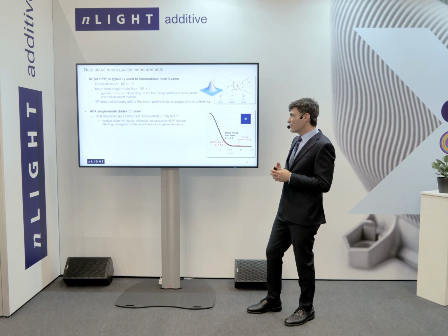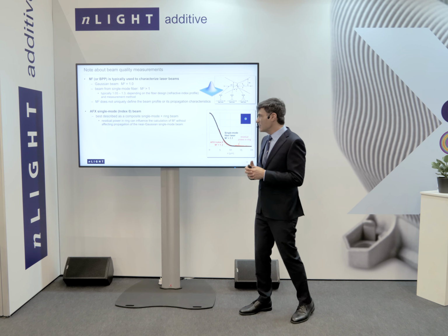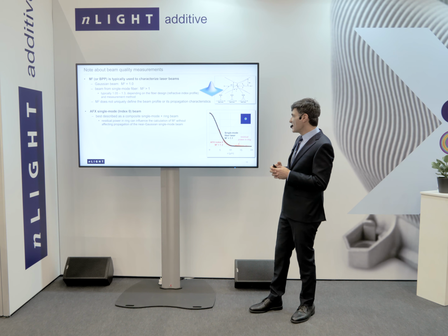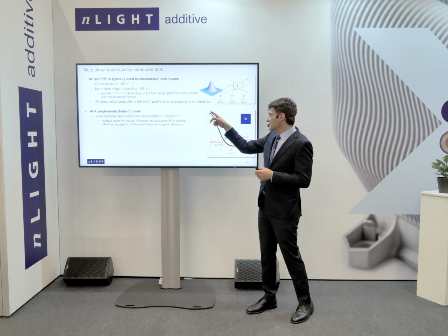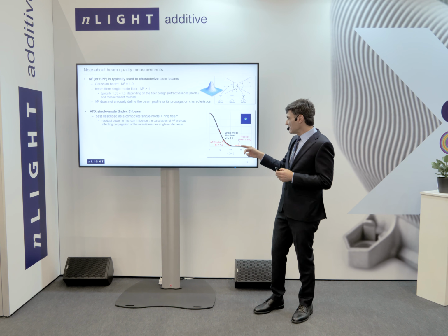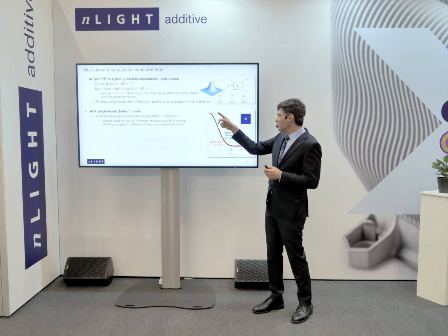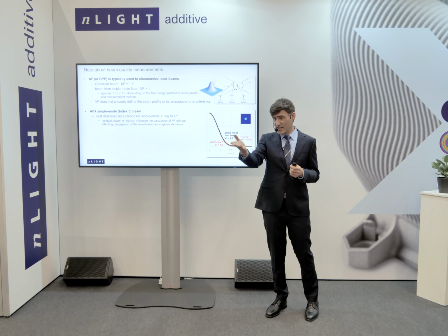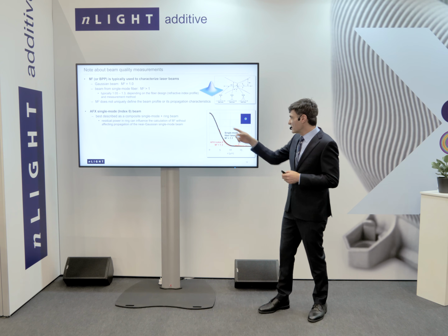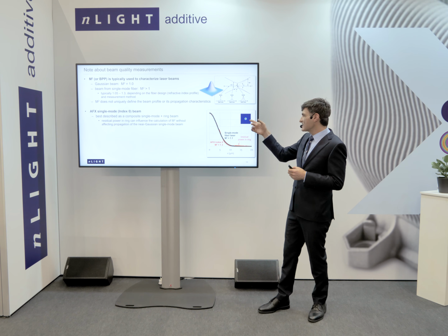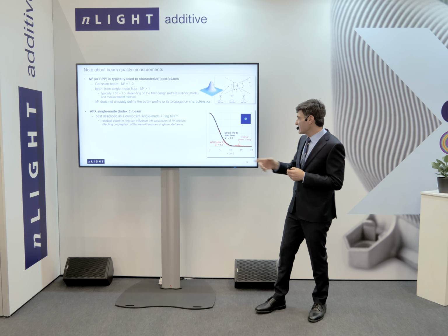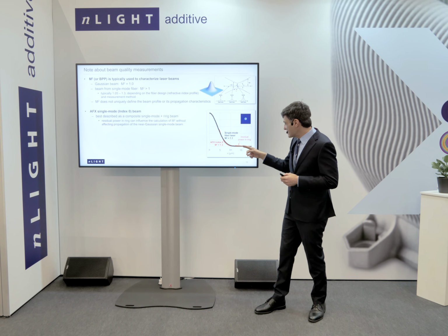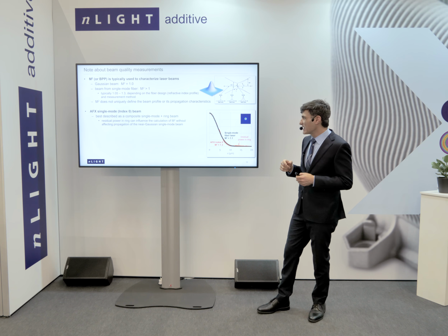If we look at the Afx index 0 beam, it's really best described as a sum of a standard single mode fiber beam and a little bit of power in the ring. In black is the profile of the beam out of one of our standard single mode fiber lasers, and in red is the profile out of Afx in its single mode index 0 setting. You see it's basically the same, but you have this little bit of power in the ring.